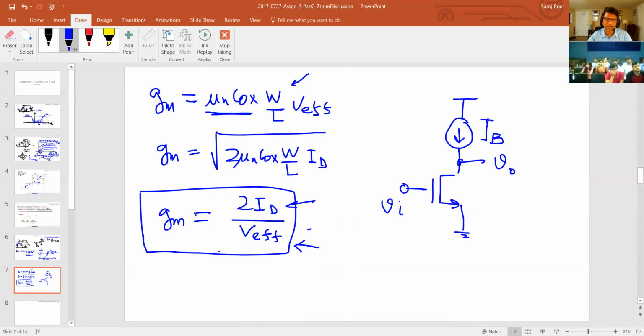And this is really a useful equation because let's say I tell you, okay, maximize this gain. So you say, okay, I need to find gm times rds, which is actually 2 over λ V effective. And typically in an IC design, in any project, you'll be given a certain supply. For example, this will be VDD, which can be your battery voltage.